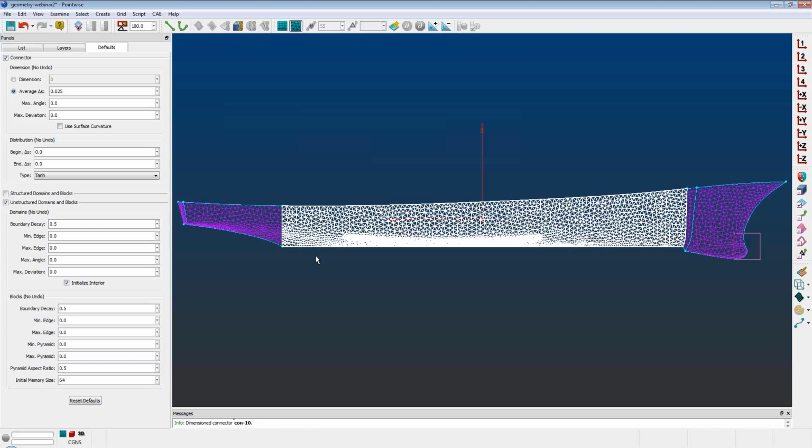You're right. Again, this is assuming you're doing this in batch mode. Let's say you had a process you'd done manually in the GUI once, and you had a pretty reliable process for making a solid from your IGES file to fix all those gaps, and of course you could name that model. Then you could redo the same process and bring that surface mesh on. I believe it's going to be based on the names, but in that case you'll actually have control of the names, because you could go ahead and name them.